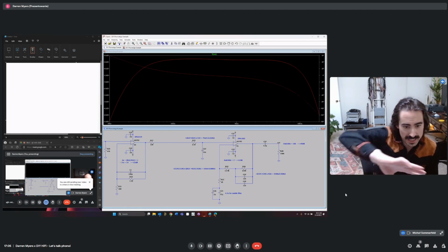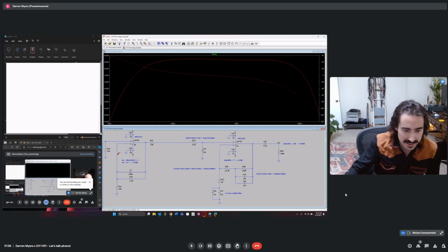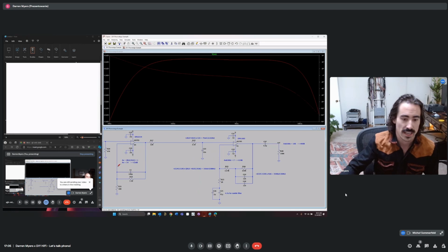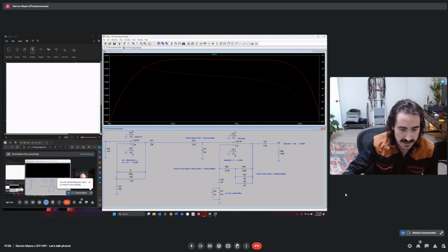So you kind of rotate it all around and then look into this node right here. Let's look at the impedance at this point. What we have is low impedance coming down here. It might as well be ground, if we wanted to simulate what these impedances look like. This is ultra low impedance. And so we have R22 in parallel with R21.